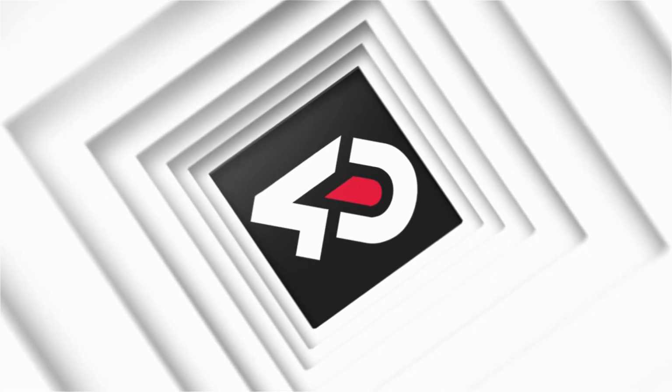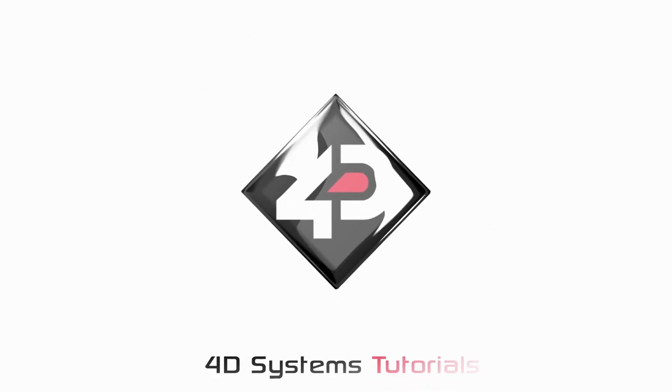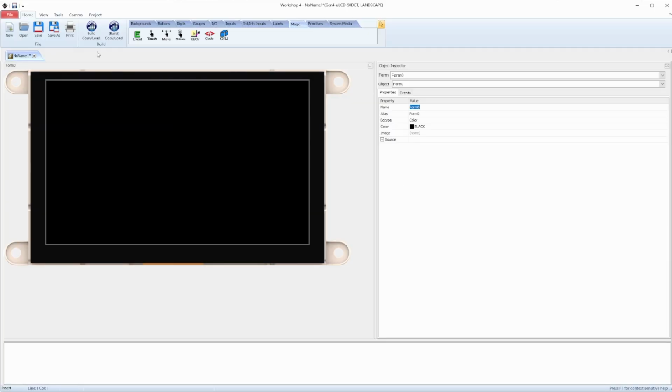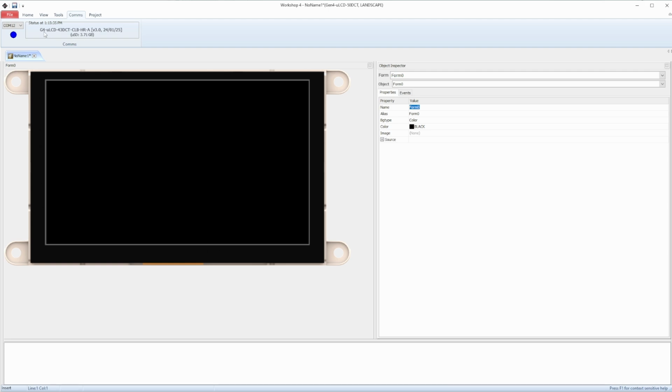In this 4D Systems quick guide, I'm going to show you how to update the PmmC firmware on a Diablo16 display. If Workshop 4 is showing your PmmC driver version in red, or your display is behaving strangely, this is one of the first things that you should check.